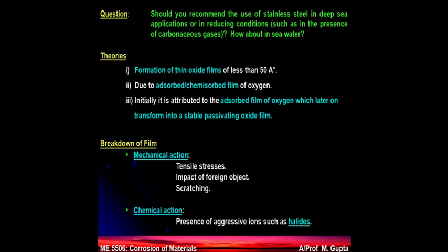Remember, I pointed your attention towards active stainless steel and passive stainless steel. The active stainless steel is the one which cannot form the chromium oxide layer, and the passive stainless steel is the one with the chromium oxide layer. If you look at the galvanic series in your lecture notes, you see how different they are. So now you have a partly damaged area and you have a totally covered area.